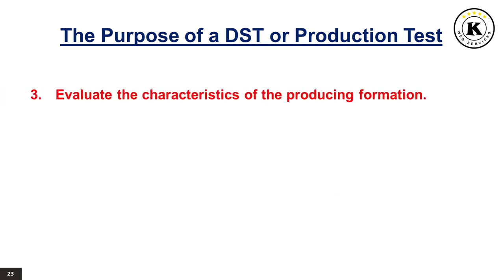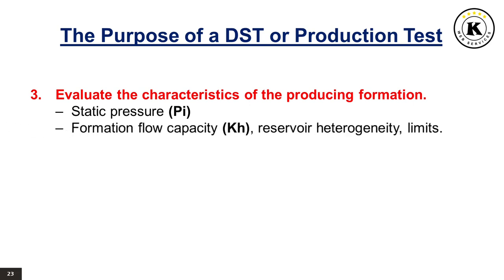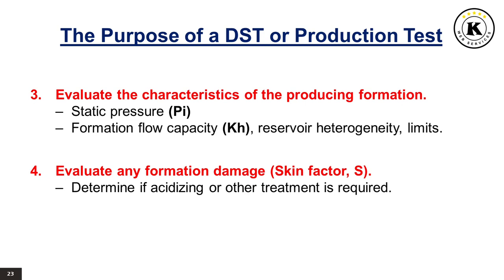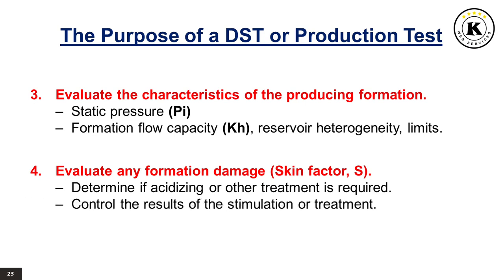3. Evaluate the characteristics of the producing formation. Determine static pressure, PI, and formation flow capacity, KH, for reservoir heterogeneity and limits. 4. Evaluate any formation damage, skin factor, S. Determine if acidizing or other treatment is required and control the results of the stimulation or treatment.